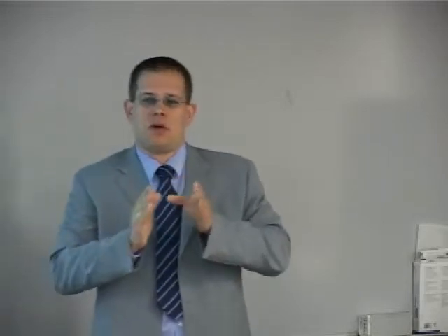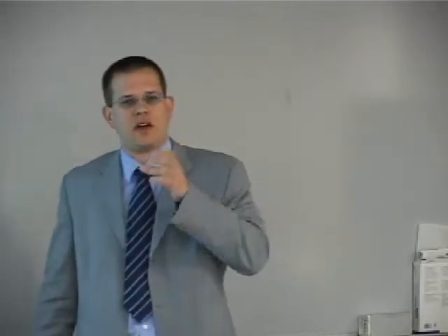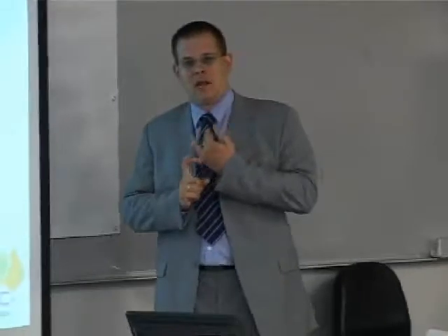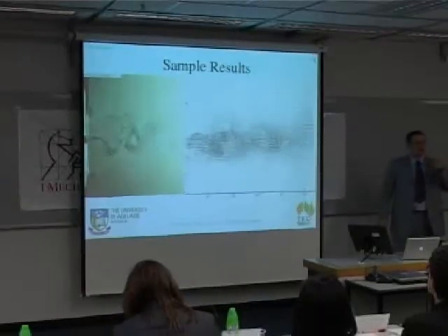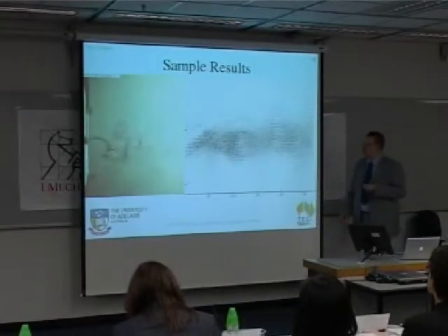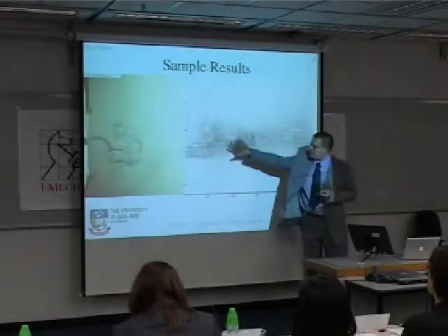In our case, doing research in mechanical engineering, we're using something called PIV, particle image velocimetry, which is a camera which can take two very quick images behind each other and then uses statistics to analyze the fluid dynamics flow, to be able to directly cut down the time you will need for experiments, because we've gone and taken these PIV measurements, and this is exactly the same flow.